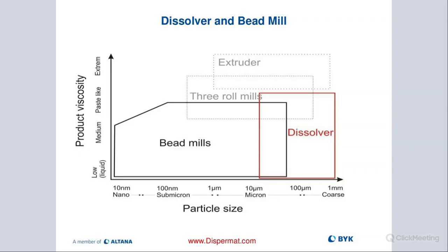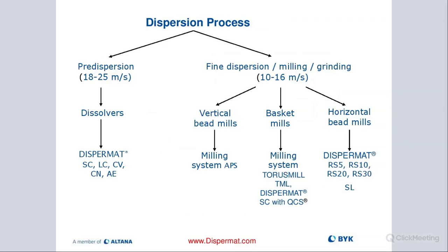It's very difficult to go below 10 microns for most of the products just using a blade, because we only have a certain amount of energy we can put in with the blade and the teeth design. There's just a limited amount of efficient shear stress to allow us to get down to the 10 micron range. Anything smaller than that is very difficult to achieve by just using a blade with teeth. We just don't have enough energy input to get any smaller for most of the products.